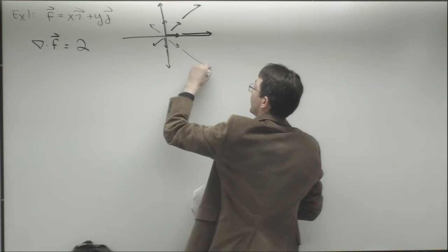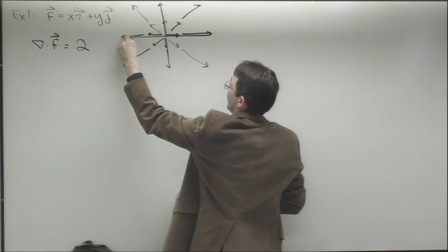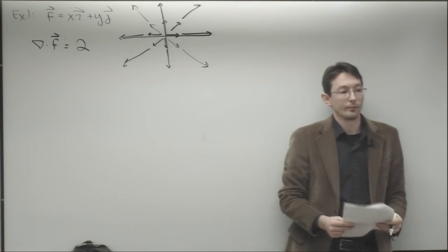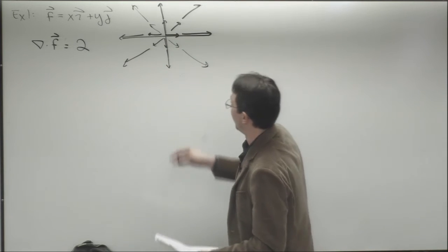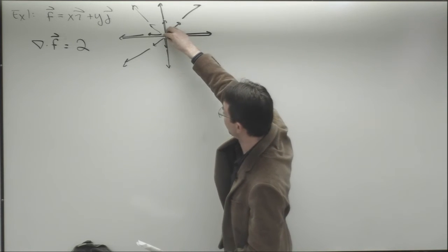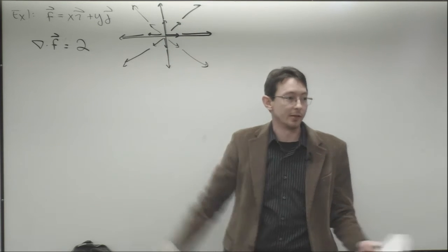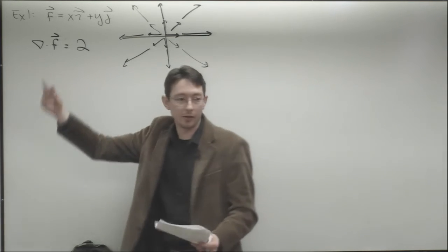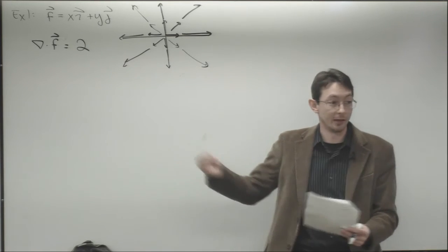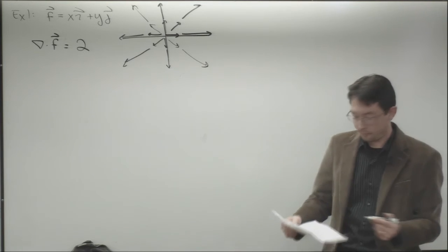So in all directions, this thing is kind of expanding outward and accelerating as it goes. Okay? A positive divergence means essentially that my flow field is diverging. That's why it's called divergence. This was named by people who spoke a language, and they picked a word that meant the same thing as what this actually does. Okay, so that's what the divergence does.